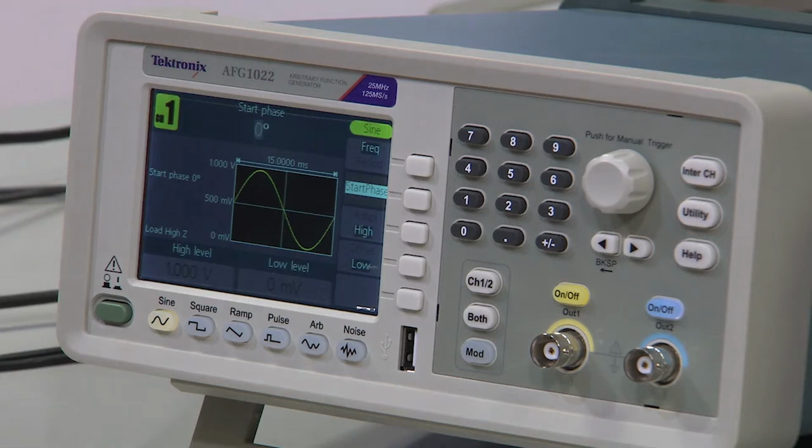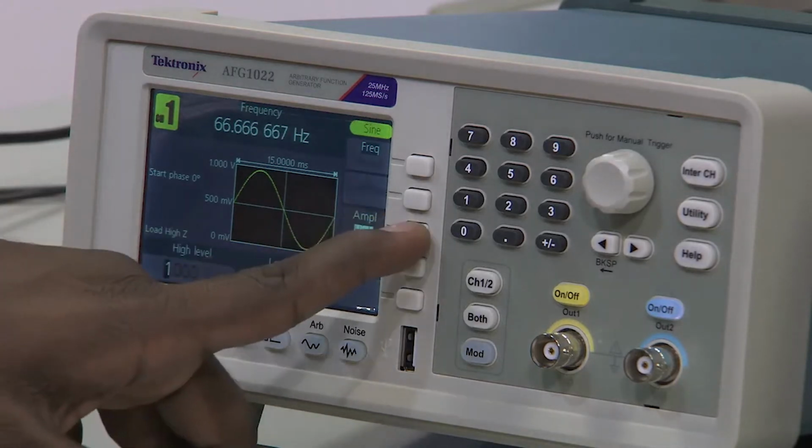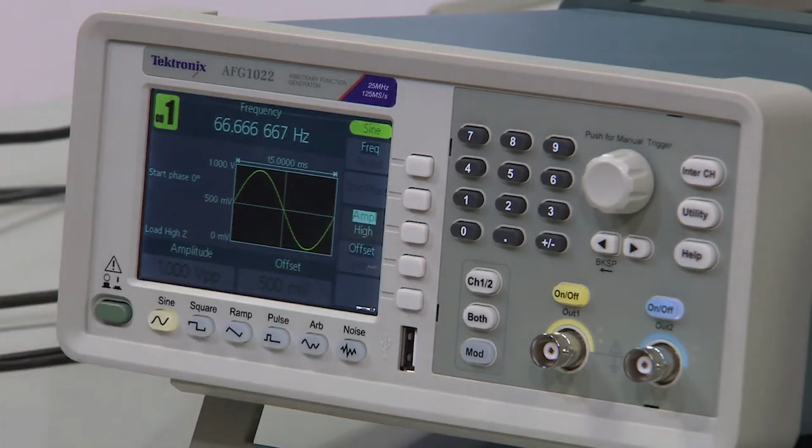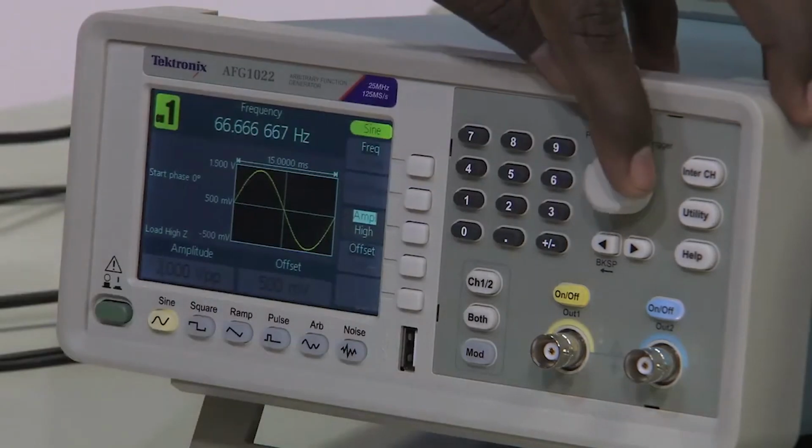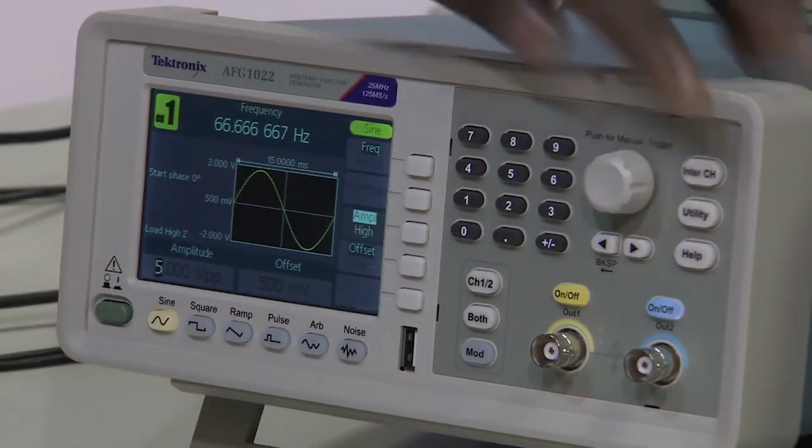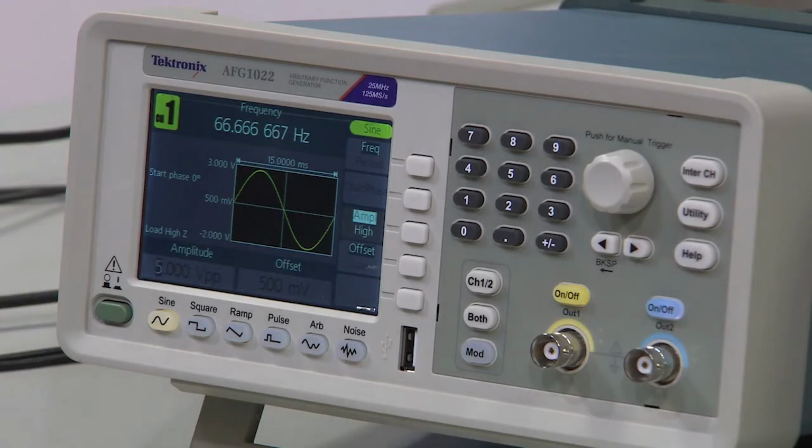Alright. Now, the next white button. We have seen this is the frequency here, and you can again change it to the amplitude, which can be whatever voltage peak to peak. Right now it is 1 volt peak to peak, you can change it to another, see, 3 volts, 4 volts, and when he is changing, you can also see the signal on the y axis, if you see minus 2 volts to 3 volts, that means the total is 5 volts. So, this is how you can see the change in the amplitude. If you want to change the amplitude, you can easily change it using the manual trigger.